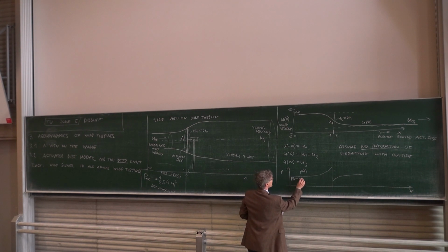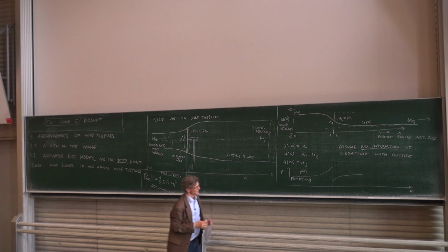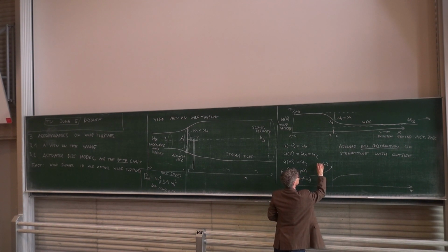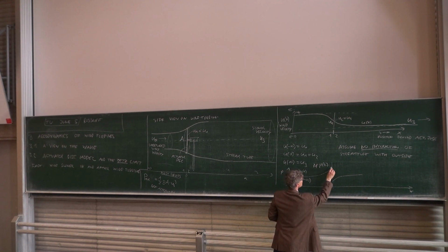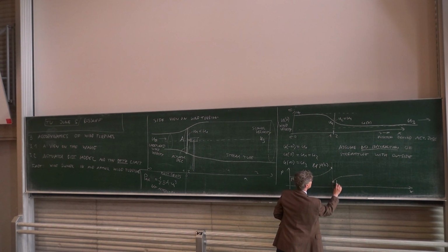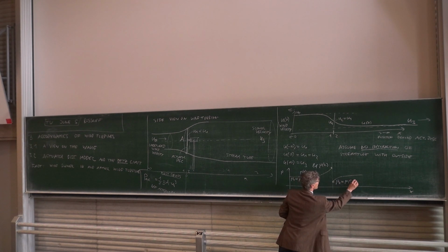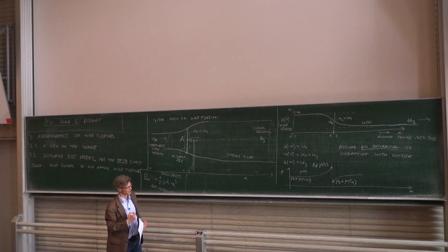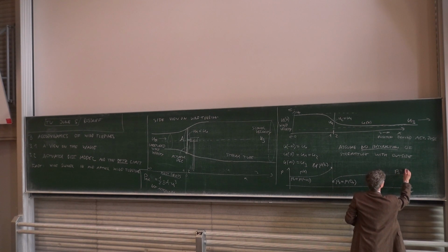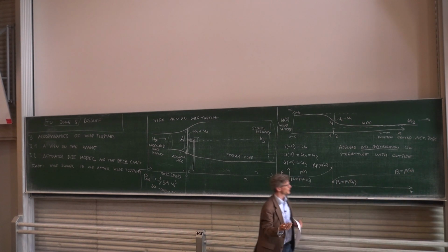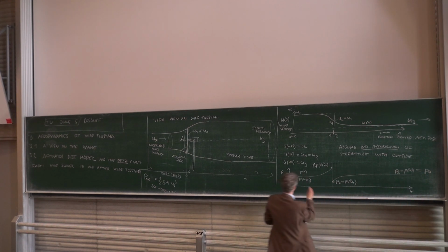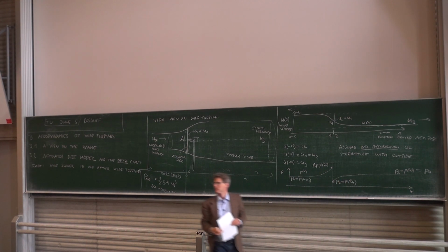P0. P0 is what I could call P at minus infinity. Then there is one pressure that I call P at 0 minus. So this is what I call P1, to make it simple. And then just behind my actuator disk, I have P2, which I call P at 0 plus. So it's just one mini point after the wind turbine. And then I will have my pressure P3 at the end, which is equal to P at plus infinity in our model, but it needs to be, and that's something we know already, equal to P0. So this level and that level must be equal in size.